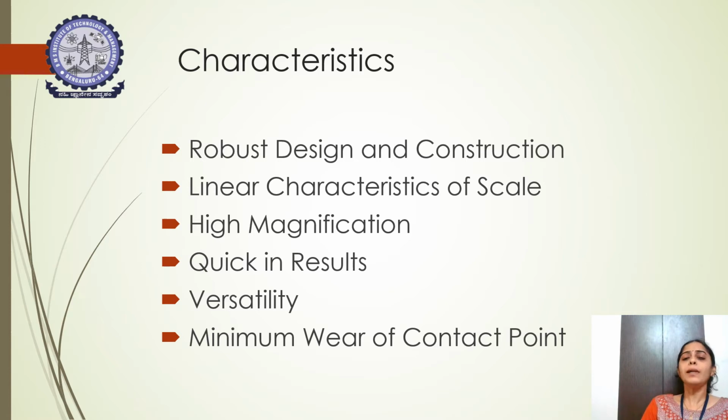And comparators yield us the result very quickly. It is very versatile in nature, and the wear which we come across while operating the comparator equipment is not too high at the contact point between the standard and the plunger, or between the workpiece and the plunger, whatever it is. So these are a few important characteristics of the comparator. If they ask you, you should list out and be able to explain each individually, at least brief it out in a proper way.